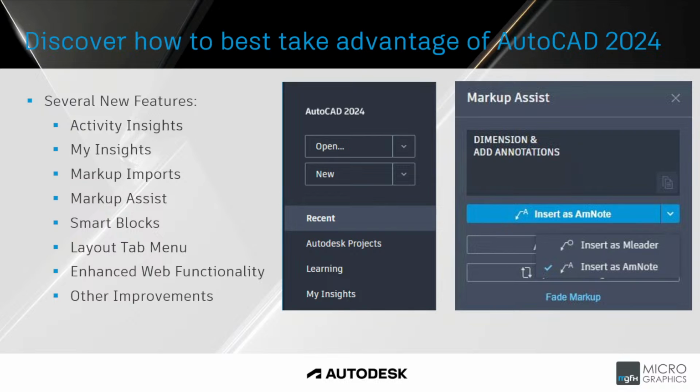To use Markup Assist, you need to enable Traceback in the command line, and then you can enable Markup Assist. While Traceback is on, you can toggle Markup Assist on or off. Choosing a Markup Assist boundary border now selects all AutoCAD items within it. It is similar to creating a revision cloud.